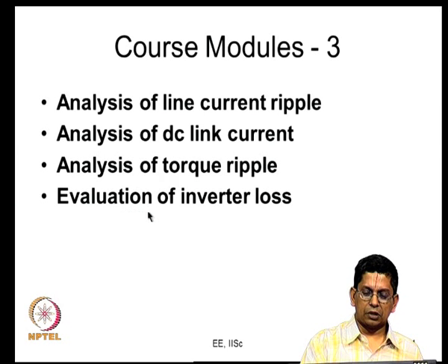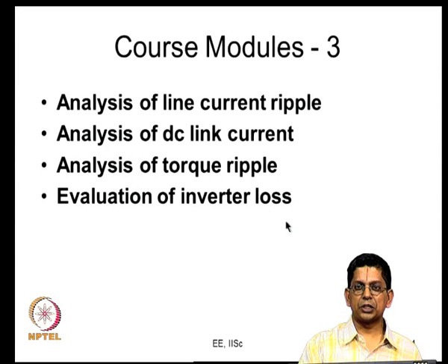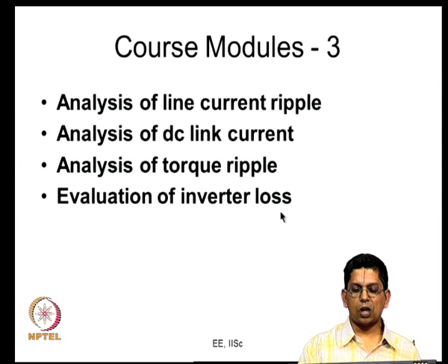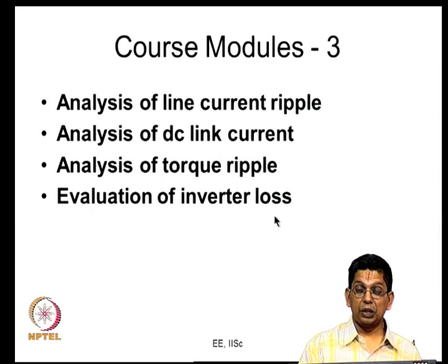In this module we had 3 lectures, the first one focusing on conduction loss, the second focusing on switching loss, and the third one exclusively focused on this reduction. We looked at these advanced bus clamping PWM methods, and we saw at least some directions in that regard, how they could be used to reduce the inverter switching loss and also the power conversion loss.